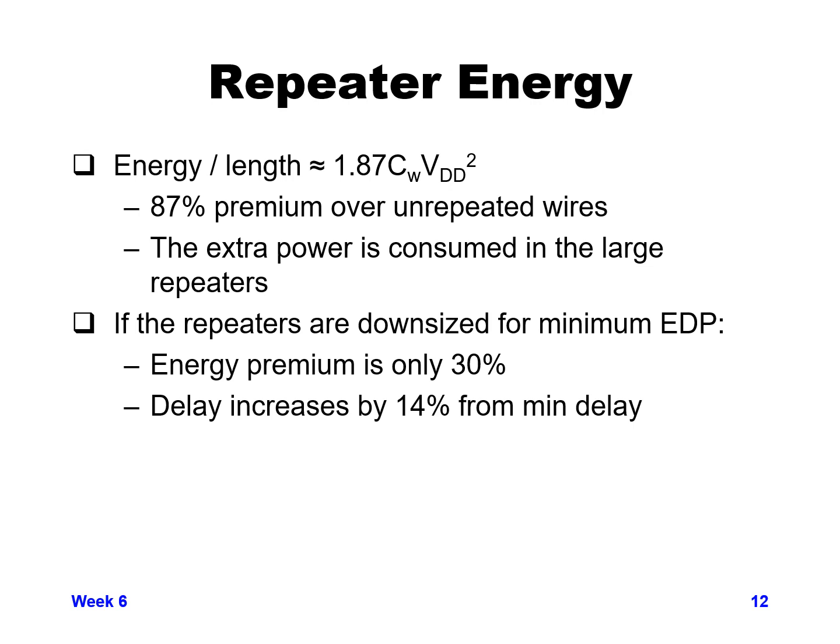Instead of being 80%, maybe down to just 30%, or even down to 15% or so, by not going to the absolute minimum delay, but by using a non-optimal delay but lower power solution. And so most of the time that type of trade-off is done in industry. You don't necessarily always want the absolute minimum delay, but you're balancing delay with power consumption on a continual basis.